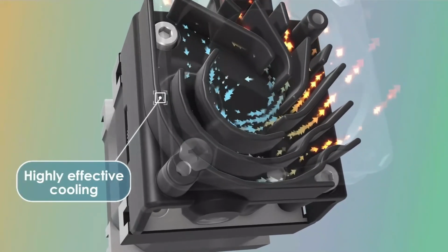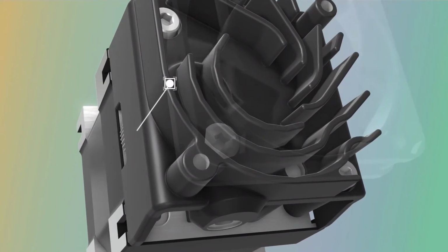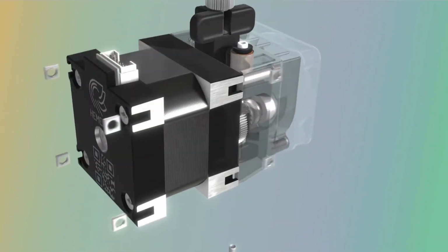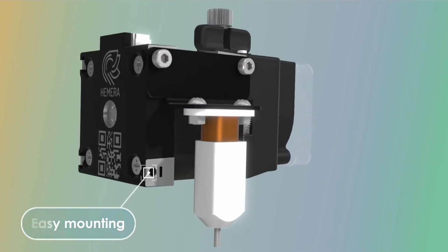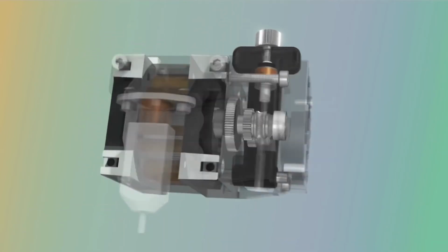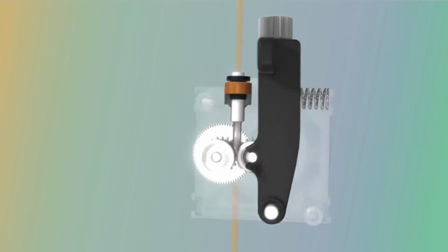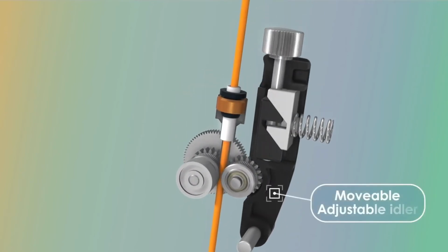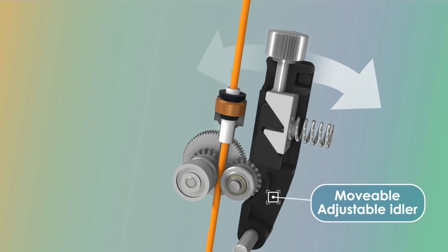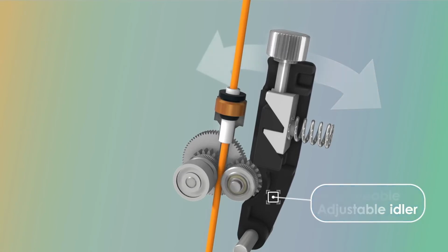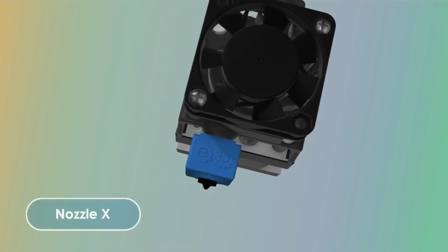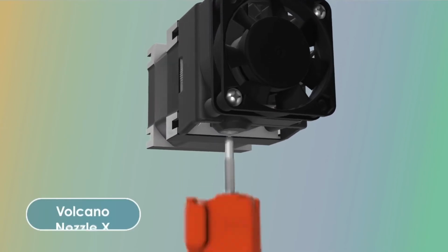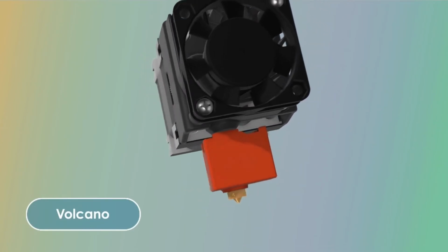From this point forward, the control system knows where the tool head and build platform are and calculates all adjustments going forward from this known position. Two, the triggering of an auto-leveling script that probes several points on the build plate to make slight adjustments to each aspect of the motion telemetry. This helps to make sure that the build plate, the area that the nozzle on the tool head can access, is true to the manual calibration of the build plate.